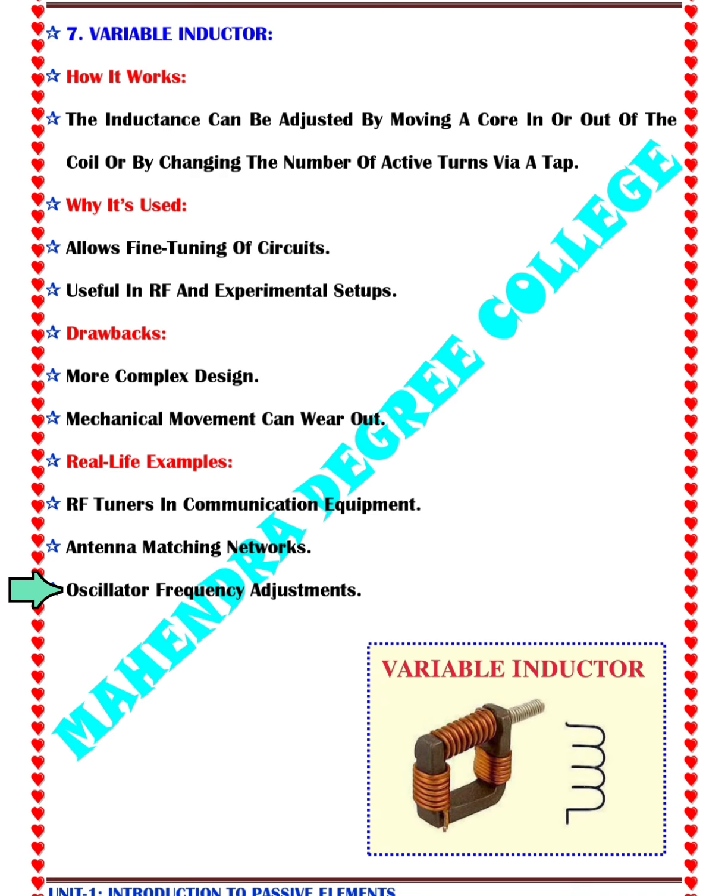Oscillator frequency adjustments. It means in LC oscillators, changing the inductance shifts the oscillation frequency. Useful in signal generators, radio frequency circuits, and testing equipment to obtain accurate frequencies.